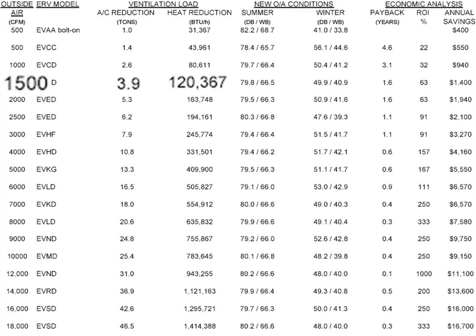On that design day when it's 95, 76 outside in the summertime, after the air leaves my ERV wheel, it's going to be 80, 67. That's usually what we target in our office as a design condition leaving the wheel on a design day. The reason we pick 80, 67, and we can certainly design wheels and other ERV types that get us better than 80, 67, so lower, but we pick 80, 67 because it's a very nice compromise of first cost of the ERV and productivity of the ERV, efficiency if you will.